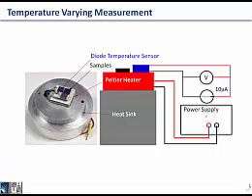And we adjust the temperature by putting these device chips, each small square chip, as you can see here, has millions of device holes on it and can have many flakes on them. We put them on a Peltier heater and cooler, which allows us to vary the device temperature. Mounted right next to them is a diode temperature sensor that tells me what the device temperature is. I can both control the temperature and read out the device temperature using this setup.